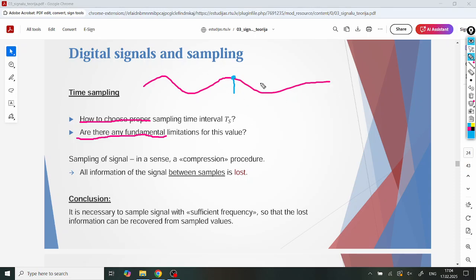That is the problem, that whenever you do this sampling, like so, from the real signal, your continuous line is gone, and you are left just with these samples. And it depends entirely on whether you have a sufficient number of these samples, enough of them, whether you will be able to reconstruct this original line from these samples.